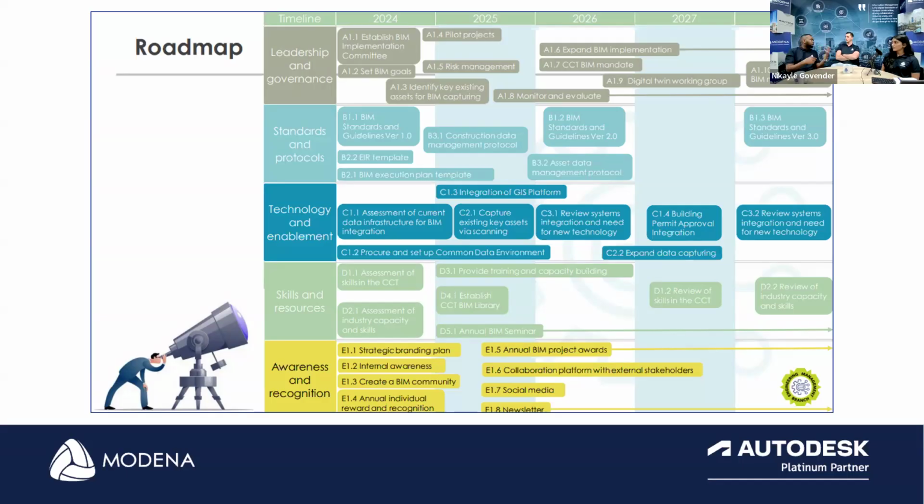On projects that make use of assets within ACC, you can document assets, let's say escalators, air conditioning units, all these little things you have on site: how they're going to be managed, when they were installed, who installed them, the model numbers, QR codes. All of that is integrated within that common data environment.